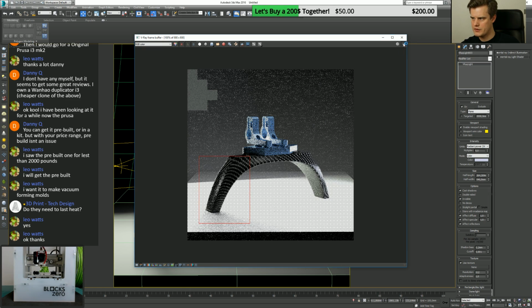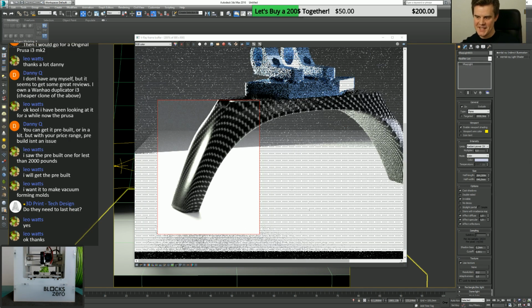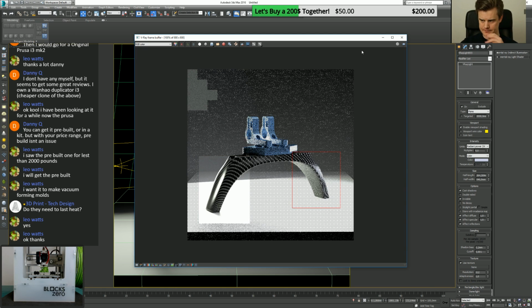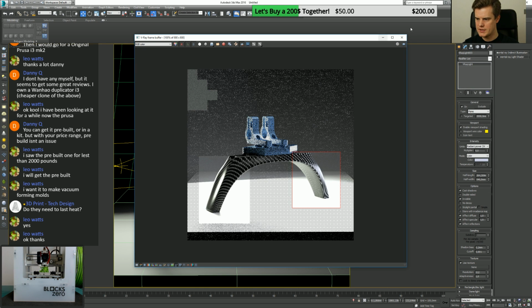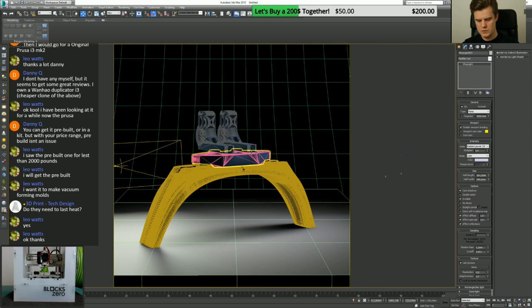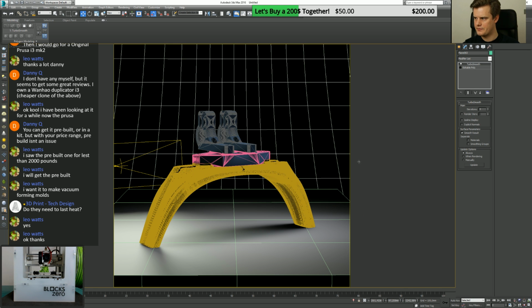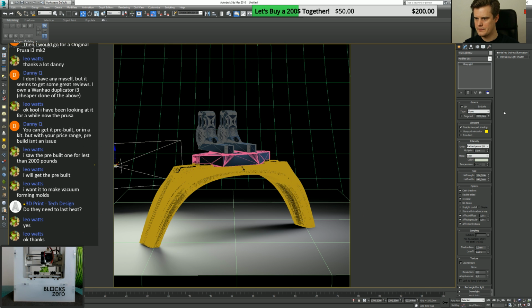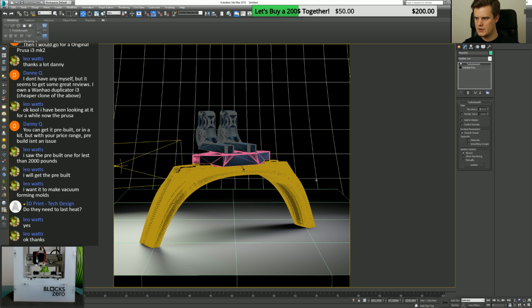Okay, Leo, if you need that, I would say that you at least need to print with HTPLA so that you can anneal it, which makes it a bit harder, and also makes it resist more heat afterwards. So it could go up to around 100 degrees, which could be okay for vacuum molding. If you need more heat than that, it's quite difficult to find materials that behave well after being printed. It depends also on the exposure time, if you have long exposures.